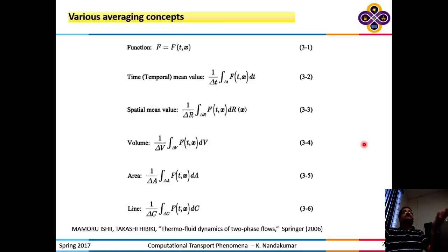Okay? And that is the approach to turbulence modeling, because we cannot predict this entire velocity field by direct numerical simulation in all industrially important flows. We apply this decomposition into a mean field equation and an equation for the perturbation variable. And when we do that, we will see what happens.